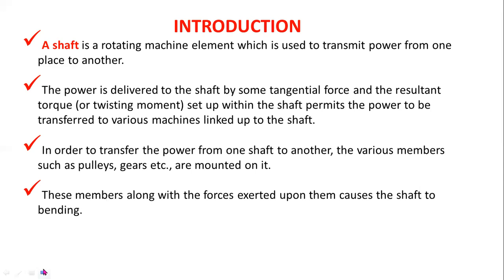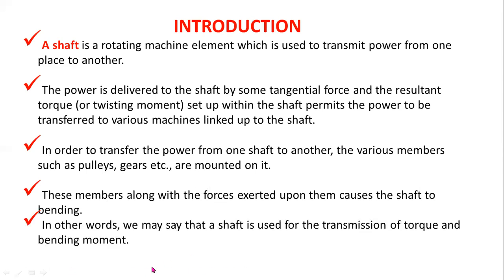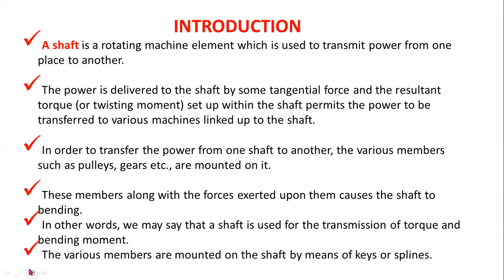These members, along with the forces exerted upon them, cause the shaft to bend. In other words, we may say that a shaft is used for transmission of torque and bending moment. The various members are mounted on the shaft by means of keys or splines.